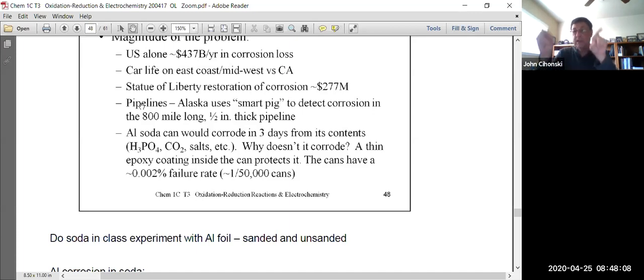So let's say you were measuring the sensitivity or the response on the inside of the pipe, and you said, okay, most of this is okay, but there's this spot where the magnetic field is too weak. Well, that would be an indication something was wrong. Maybe you had a leak or it was getting close to leaking. So what you would do is map that out electronically.